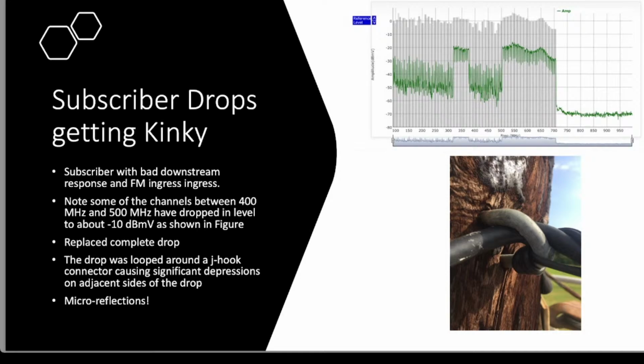Now, down on the side of the house, there was also some corrosion on the connector. And now we have two points, the kink and the corrosion on the connector on the side of the house, where we create what we call an echo cavity. We've talked a lot about echo cavities, where the signals bounce back and forth both from a cable modem and also in the downstream, and that creates the standing wave that we see in the full band capture. These are our micro reflections that we talk about so frequently, and it just creates a little bit of a dent in that. It creates a non-75 ohm impedance mismatch in our coax cable.